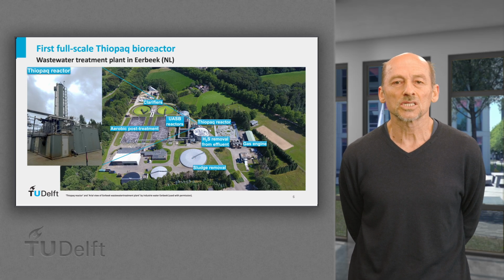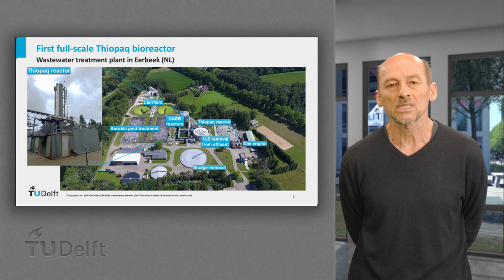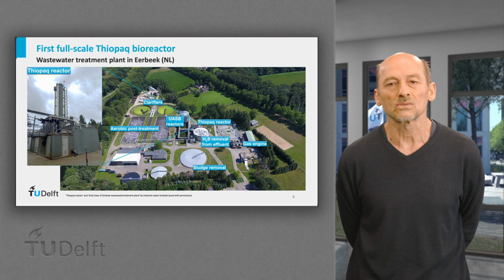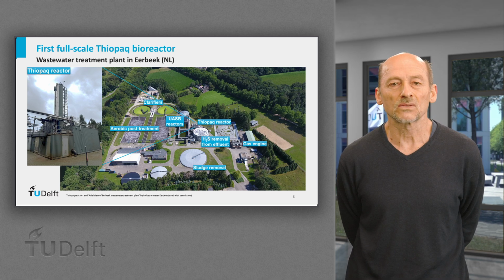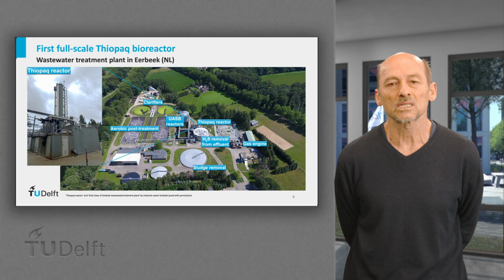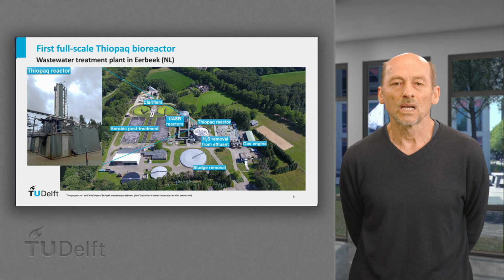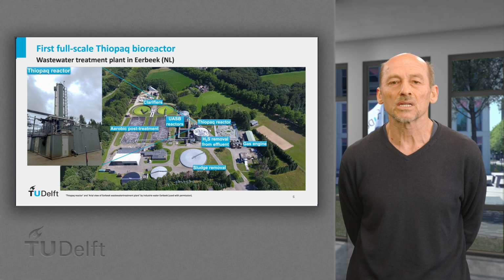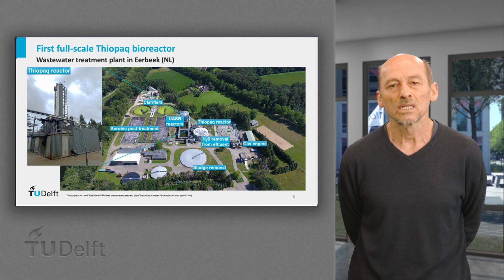This is the first full-scale THIOPAQ plant in the Netherlands, operational since 1993, purifying biogas produced by anaerobic digestion of wastewater from 3 paper factories. The biogas consisted of 80–90% of methane, 1% H2S, and the rest as CO2. At the outset, it operated at pH 8, selecting for a neutrophilic marine sulfur-oxidizing bacterium Halothiobacillus neapolitanus as the dominant organism. However, after shifting the operation pH toward 9 to increase the H2S scrubbing efficiency, this bacterium was gradually replaced by another, more alkali-tolerant population.